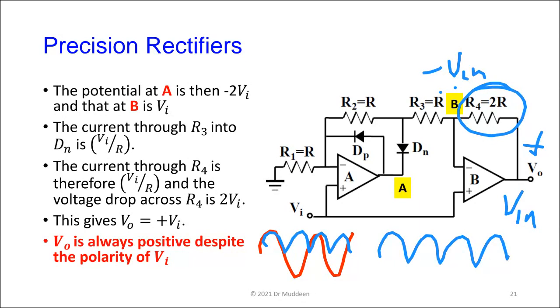The only thing that we have inside of here now is that we have these 2 diodes. And notice the diodes are doing nothing but connecting or disconnecting the op amp to the rest of the circuit. They're not doing any of the rectifying action at all. They're just used, for want of a better word, as electronic valves, or maybe switches might be a better word. So they're either on or they're off.